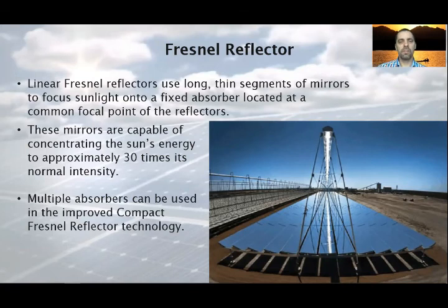The Fresnel linear reflector is a system of concentration of solar radiation similar to parabolic trough mirrors. In this case, these linear solar collectors carry normal flat mirrors and simulate the curvature of parabolic trough mirrors, which are more expensive, by varying the angle of each row with a single tracking axis. The main advantage of the Fresnel linear receiver system is its simple installation and its low cost, although the energy efficiency is lower than the parabolic cylinder collector technology.